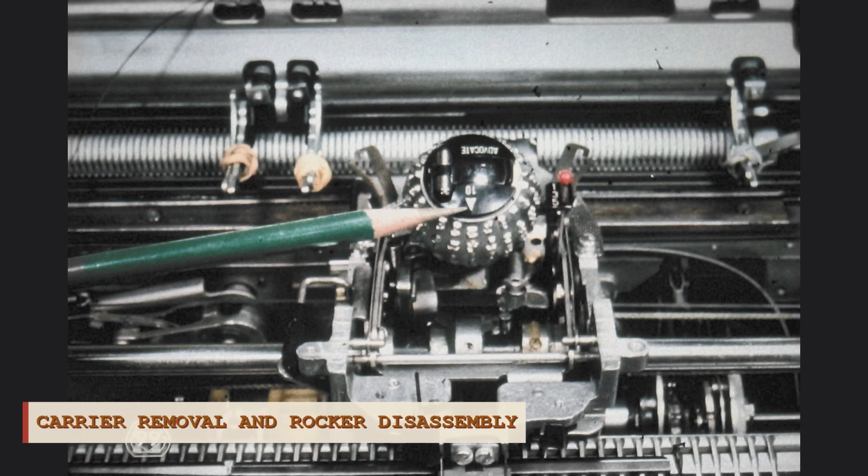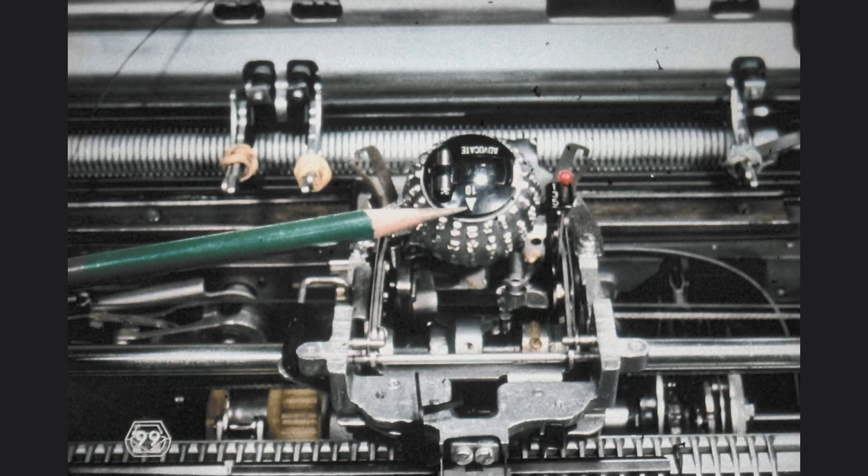Notice the indicated small arrow on top of the type element. It is now possible for us to release the rotate spring tension and tell exactly how many turns it takes for the element to come to rest. In other words, we can find out how many turns of spring tension are loaded into the rotate spring when the system is completely assembled.